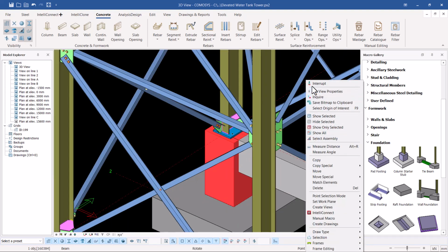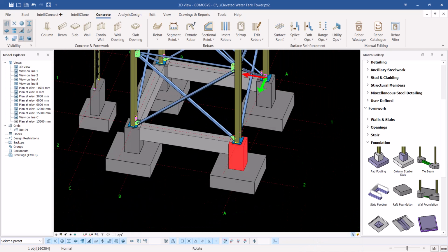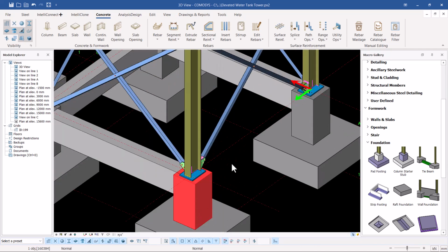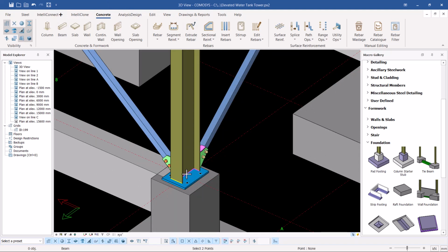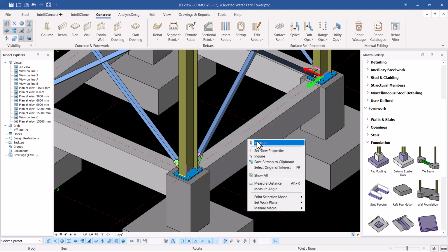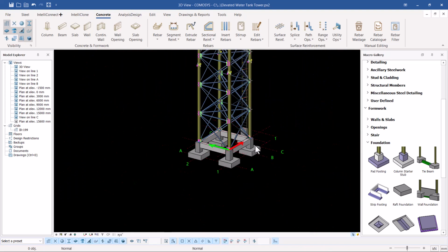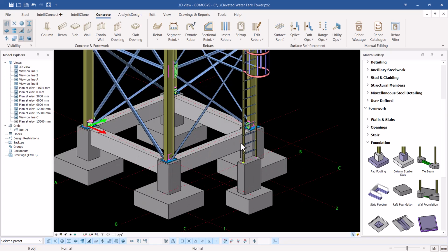So if I turn it round like that, I'll be able to see that my beams are in the right location. So I'll come back and finalize with this. Just mouse over accurately so that you snap on the right location, and I'll snap right here, right there. So I have my beams in place. You can see my beams in place. So exactly what is remaining is just placement of the rebars.